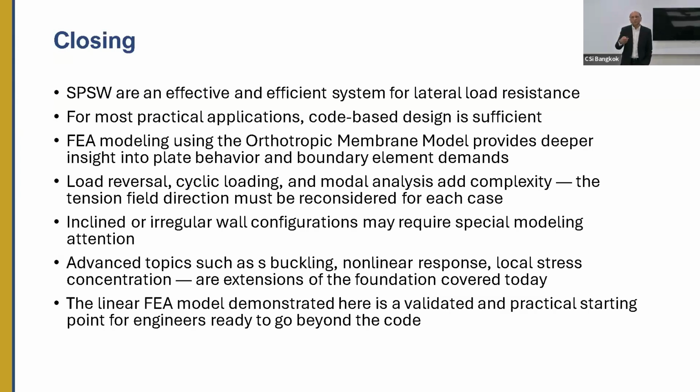Then we cannot use this predetermined direction of the material because the loads will be reversing, and the model will not reverse. So there are many solutions to that. One is that you use double elements, each element at each location, one element with half thickness, like we do for the brace, and then assign the half plate this way, half plate that way.